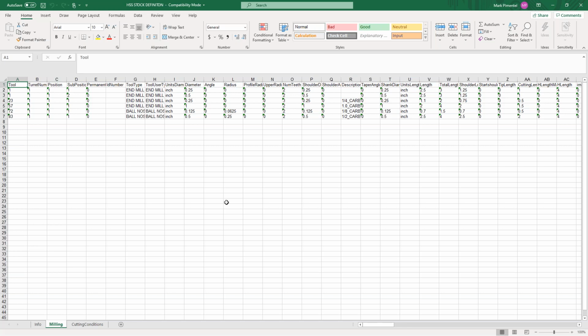So you can actually use Excel features here to just incrementally increase. Let's say you want to do 1/4 of an inch, 1/2 inch, 3/8, 3/16. You want to just do the range of tools there. You can do your math, or use features, to get that to auto-populate. And if you've got many of them, this is an easy way to load all of them in one click. It might do some thinking in the background, but then eventually you'll have a tool table that has all of this in place.